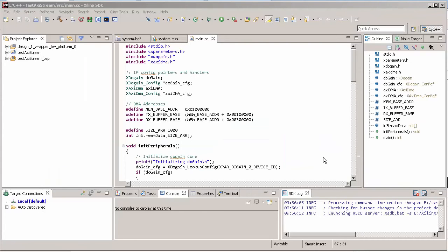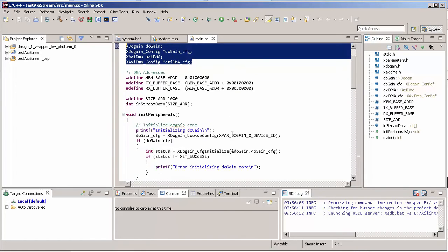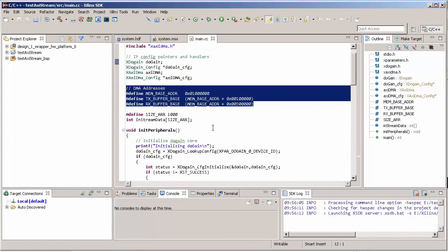So guys, basically the Xilinx SDK part to use the DMA and IP core is quite simple. Here we just include our drivers for using the DMA, and this is the exported driver from Vivado HLS. If Vivado HLS detects that you use AXI Lite, it's going to create a simple driver to help you control your IP core. Here is just the configuration interface needed. This is an important point. Let's wait a little bit and have attention here.